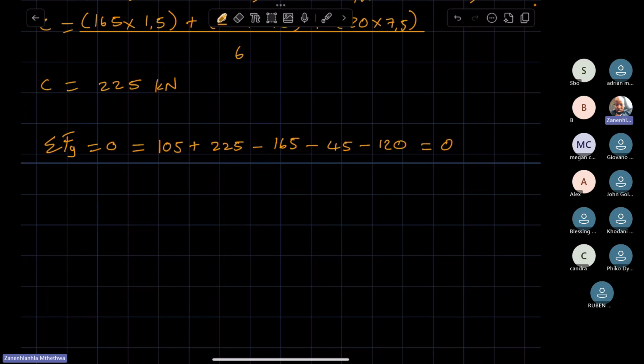If you're doing bending moment calculations, forces going down you take as being negative, forces going up you take as being positive. That's the approach I teach you. I found that this is the easiest, the simplest approach. Whether you're considering forces on the left or the right, forces going down are negative, forces going up are positive.